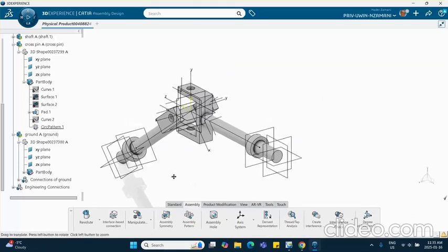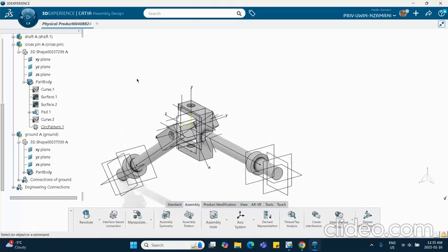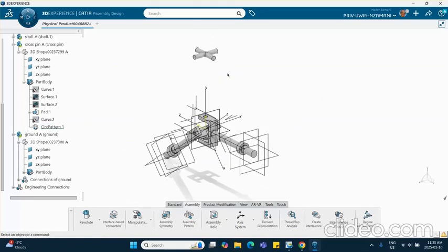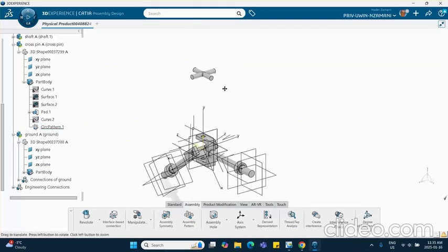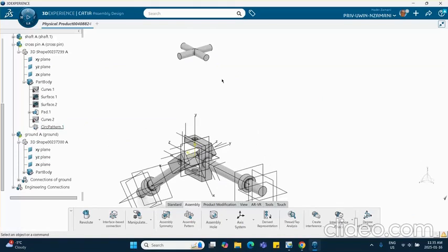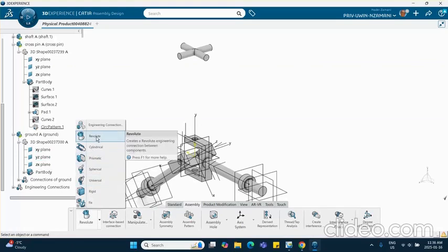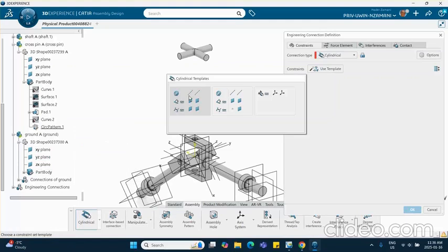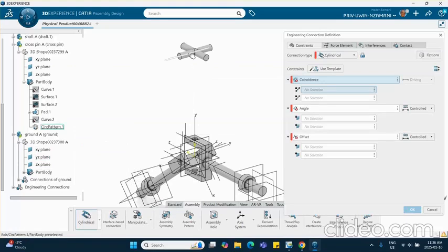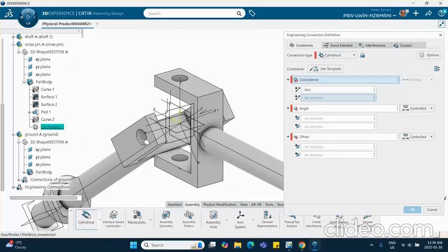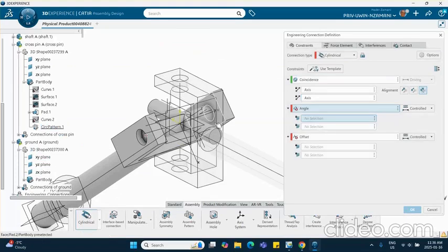Now, the universal one, but maybe I place this thing in there. So that's going to be, how about two, let's make it two cylindrical ones. If necessary, we're going to come back and fix it. Okay, so not coincidence, but two cylindrical ones. If necessary, we change it. We can use this or that, doesn't matter, because all we need is the axis of this and the axis of that.